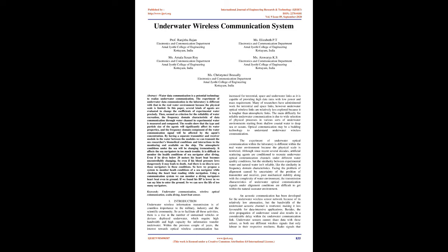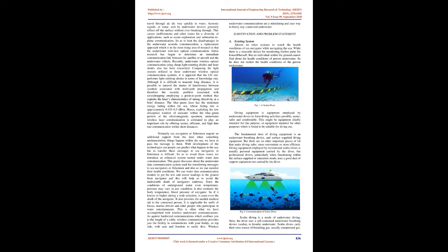Acoustic communication has been developed for the underwater wireless sensor network because of its relatively low attenuation, but the bandwidth of the underwater acoustic channel is restricted, making it less favorable for data-intensive applications. Besides, the slow propagation of underwater sound also results in a considerable delay in the underwater communication link.